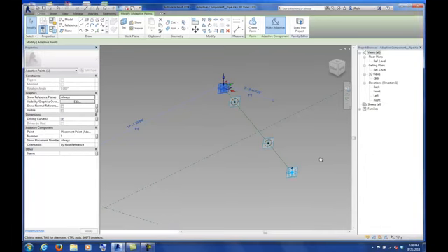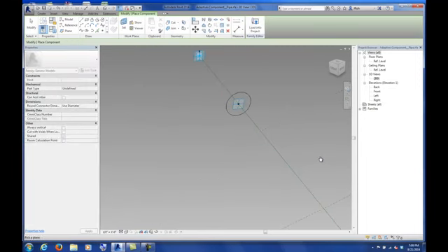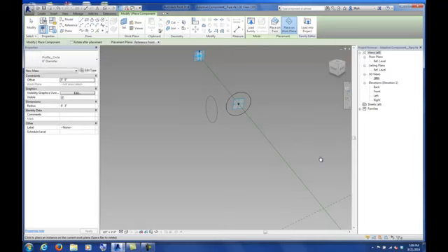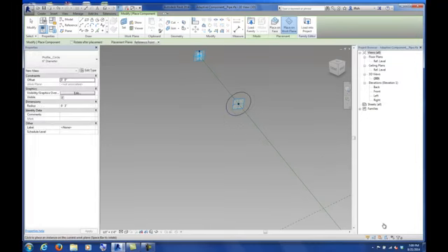So when you're picking these planes to place, you'll notice that when I hover over that point, if I hover over the center, I start seeing essentially the horizontal and the vertical axis of that plane. You see how that gets highlighted? If I were to select one of those, it ends up 90 degrees because I'm actually selecting a different plane through that point. So always make sure you're hovering over the corner so that you actually see the outline of the plane, and then it will be exactly the way that we want it to be.